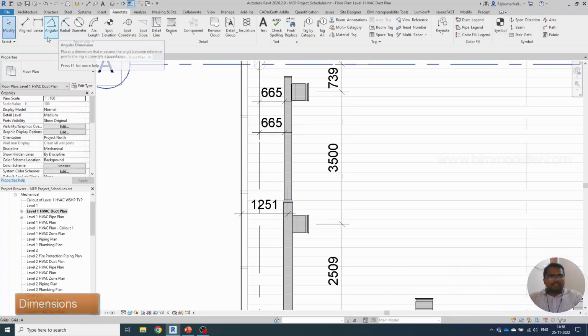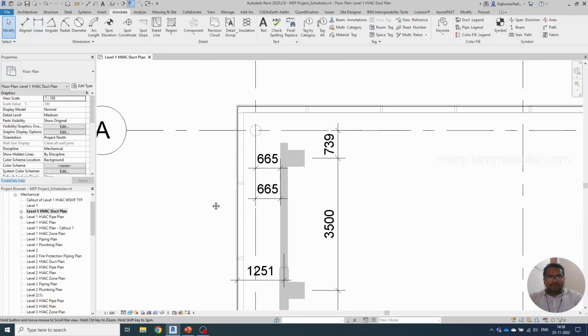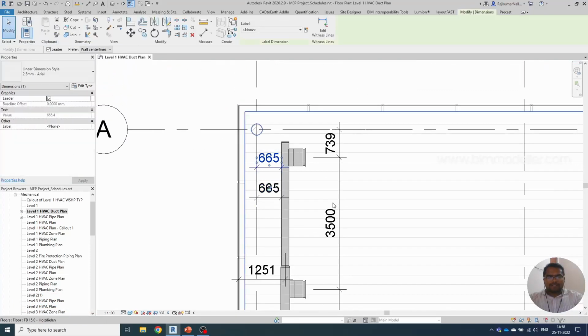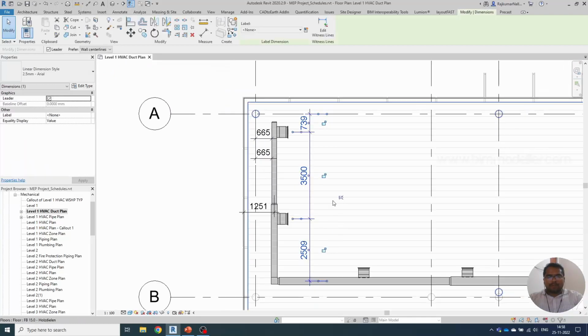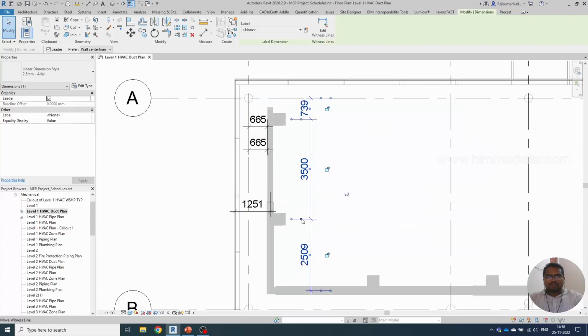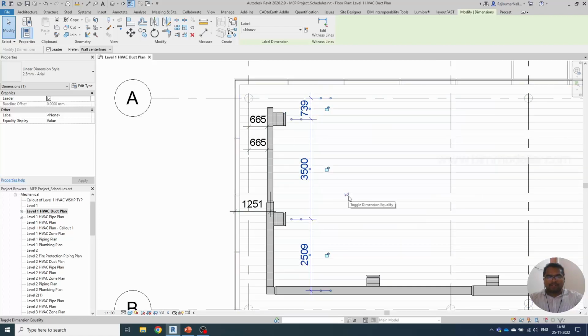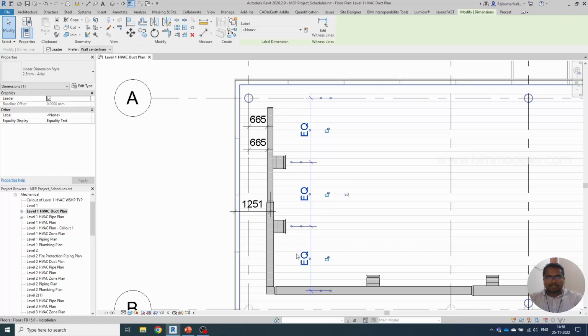You see that you have different options in the dimensions. One is the lock we have discussed, and another option is continuous dimensions, which we have discussed. You will even be able to lock one in this place and remove the other locks similar to this. In my case, I like to keep this at equal distance. For that reason, you can click this equal symbol, and automatically it will align at equal distance like this. Here the same distance in 3 places will be aligned automatically. While modeling, this will be very helpful to place elements at equal distance.